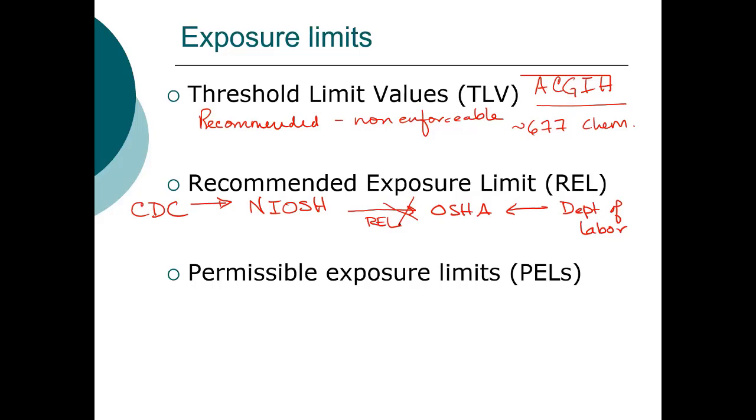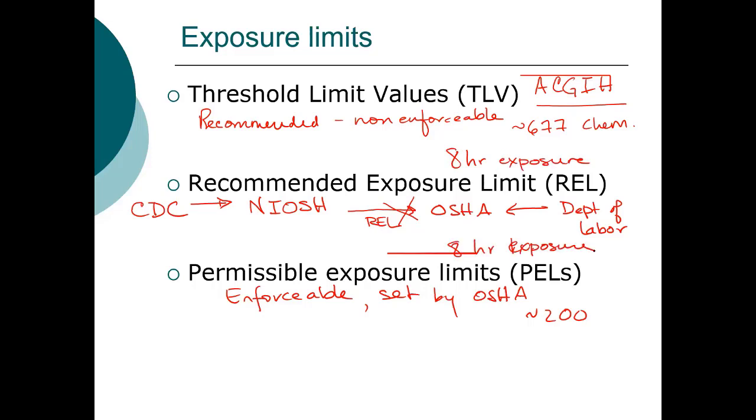OSHA sets the permissible exposure limits. So OSHA limits, these are enforceable, and they're set by OSHA. And there's far fewer. It's only about 200 or so that have been set by OSHA. So we go from recommended TLVs. Typically, these will be for 8-hour exposure. Same here. And typically also your PELs will be for 8-hour exposure, although we have different limits that have been set for different exposures, and we'll look at those.